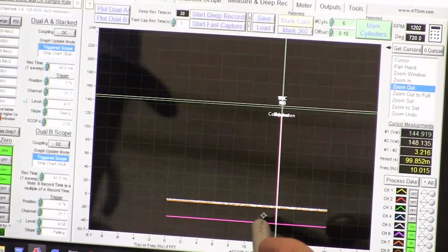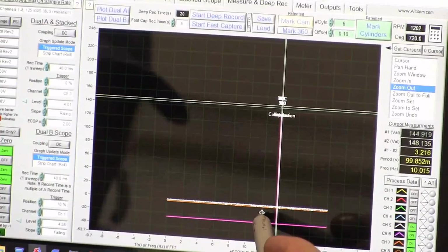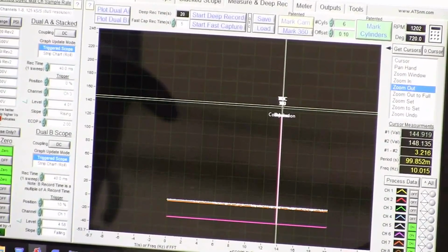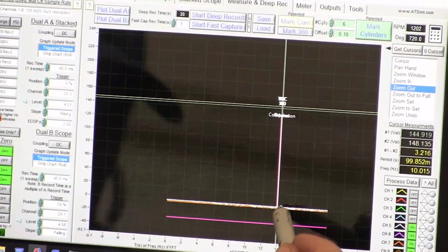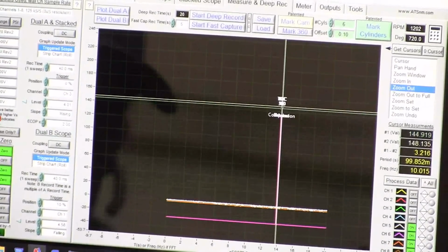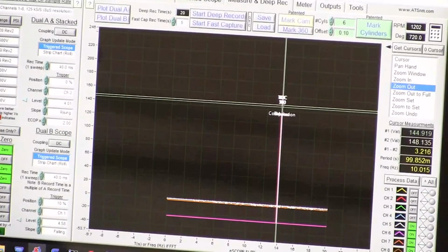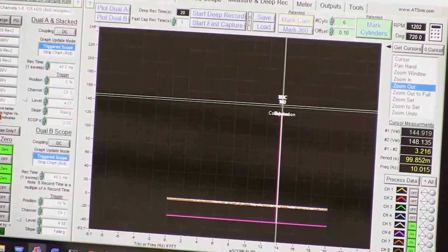That makes me think that the cam phaser is getting oil from the solenoid when it shouldn't. The solenoid should block it off and the oil is bleeding through and it's advancing that cam. So I think this is a VCT problem now. It definitely isn't controlling it.